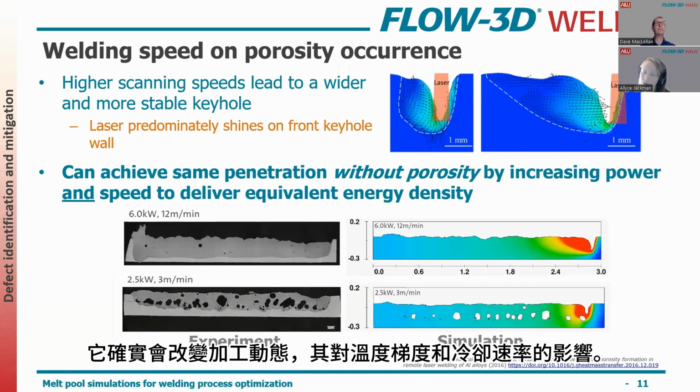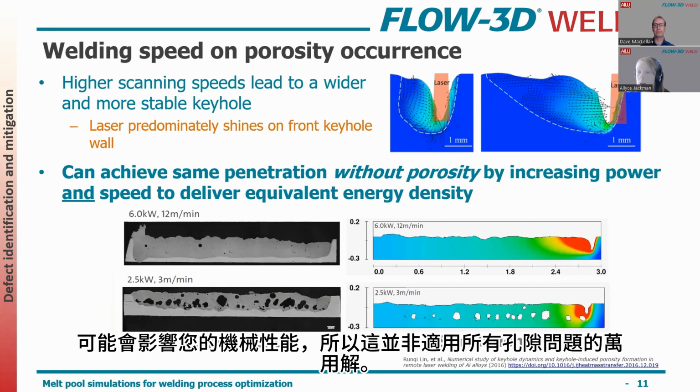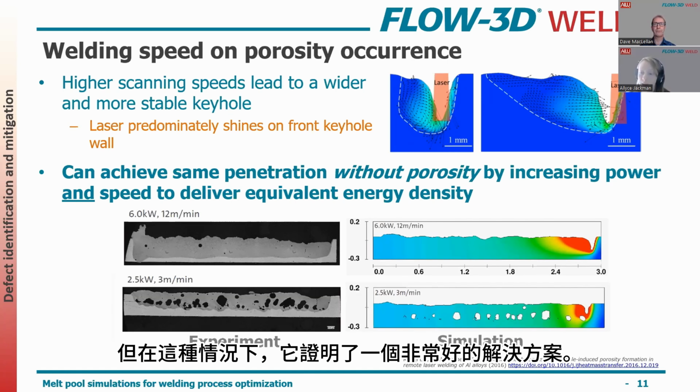It does kind of change the process dynamics. What effect it has on thermal gradients and cooling rates might impact your mechanical properties. So it's not necessarily the universal answer to all porosity, but in this case, it proved to be a very good solution.